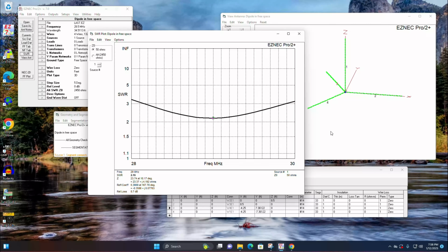Because if you remember, the vertical dipole had an impedance up around 70 ohms, which was a titch high. So a little bit high, and if we compare it to this, it's a little bit low. So what we want to do is kind of find a happy medium between those 2 points. So thus the reason for sloping the radials down.